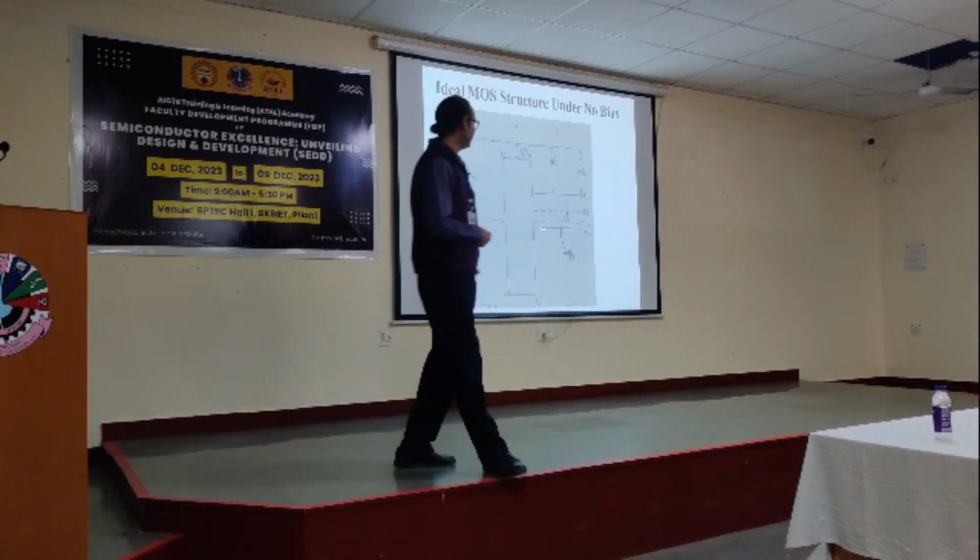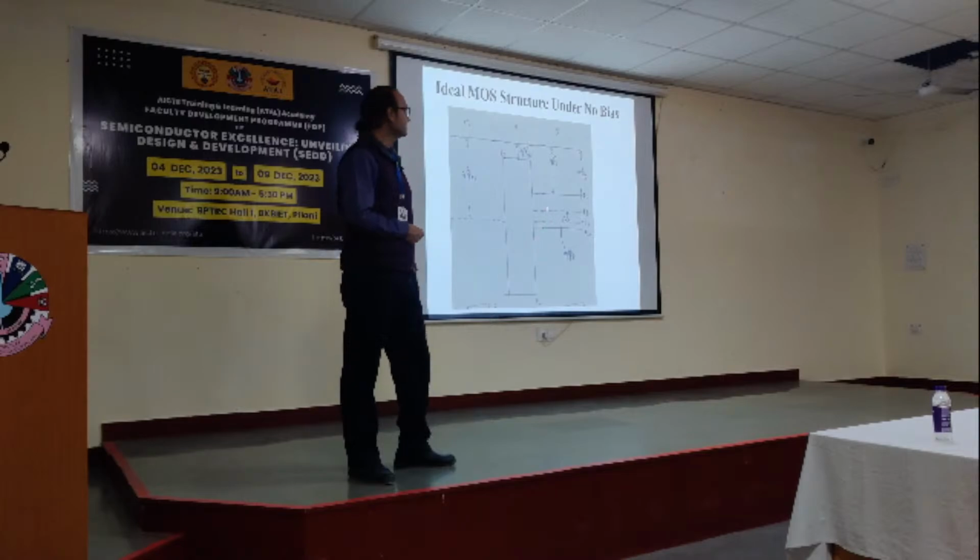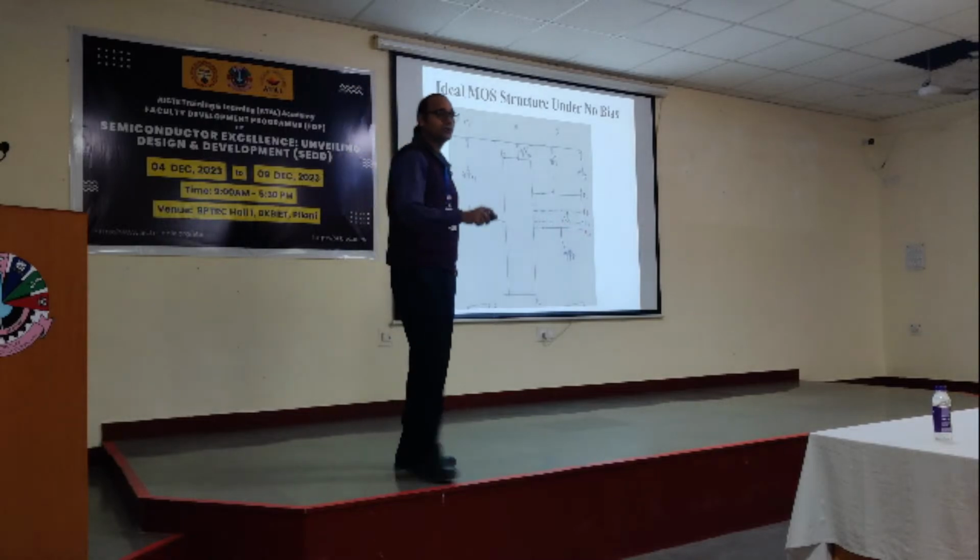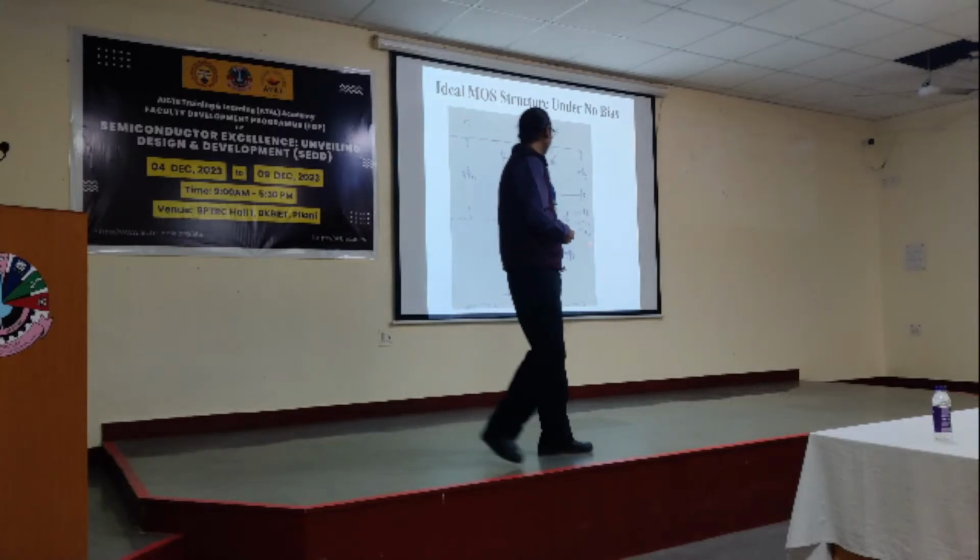Now actually we are short of electrons. So that's why the Fermi level will come down, because it tells the probability of finding an electron, right? The Fermi level will come down and come closer to the valence band because we have more holes now in that same semiconductor.